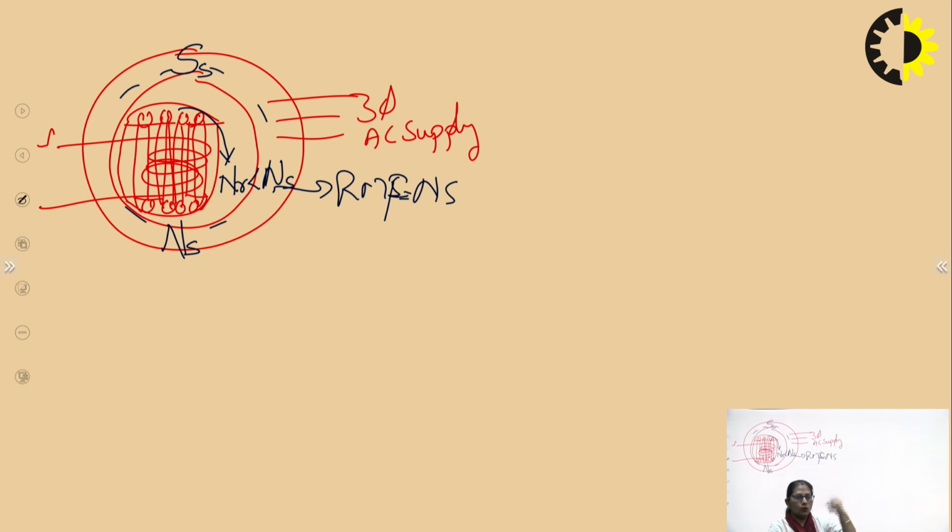Now, the rotor is rotating at almost the same speed as ns, and the rotating magnetic field is also there. Now, when we switch on the DC supply, the rotor poles would be created, right? At one instant, because it is rotating at almost the same speed, we'll have a north pole created here and a south pole created here.